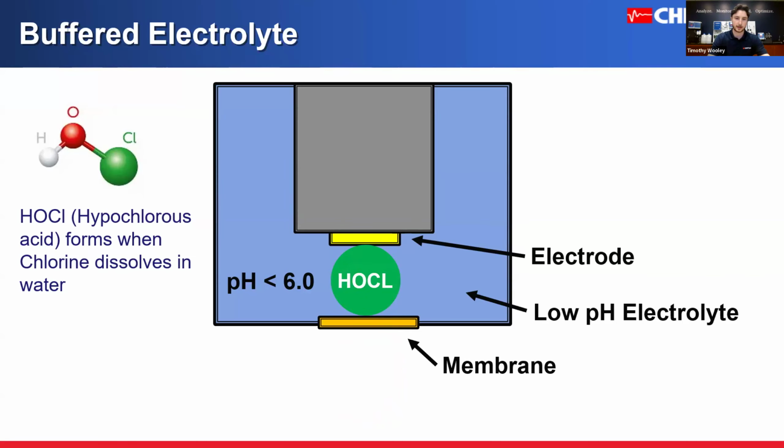This is a bit of an oversimplification because both OCl and HOCl are present in the water at both points during this reaction. However, the conversion to a hypochlorous acid dominant solution, I would say, is what is necessary to accurately read the amount of chlorine in the water.